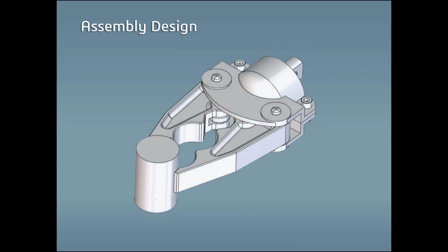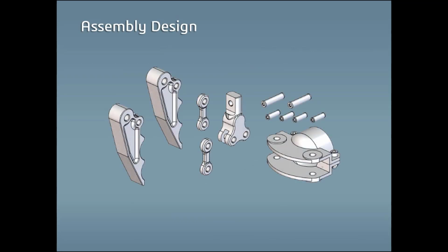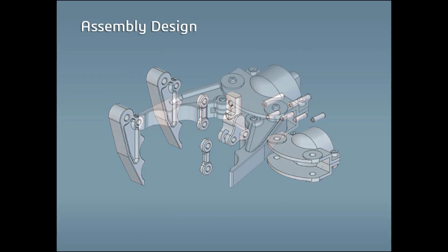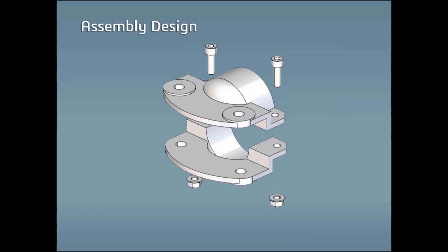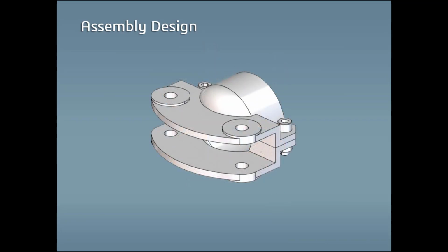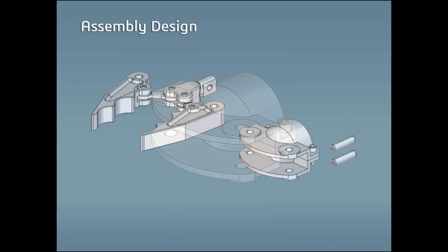Creating assemblies in xDesign is a straightforward process that should be familiar to all experienced CAD users. Existing components can be added together in a design and then mated together to produce the intended motion. One way this process can be simplified is by creating subassemblies. By mating components together in a single design, it can be saved and inserted into another assembly.